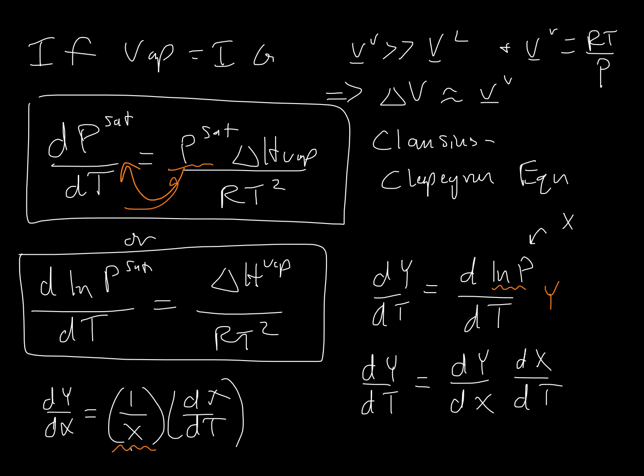Okay, one last comment about the Clausius-Clapeyron equation. Who's familiar with Antoine's equation for vapor pressures? Hopefully everyone, because that's something that people in chemical engineering use in thermo, in design, in process engineering all the time. So the Antoine equation form is usually natural log, or it could be log base 10. But it is the vapor pressure that has a form like this. It is an exponential function. Now this is an exponential function because the Clausius-Clapeyron equation is an exponential function.